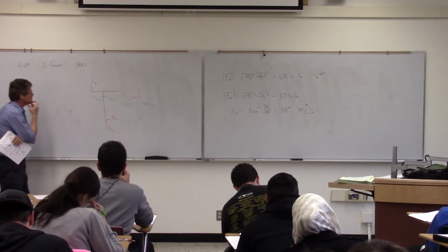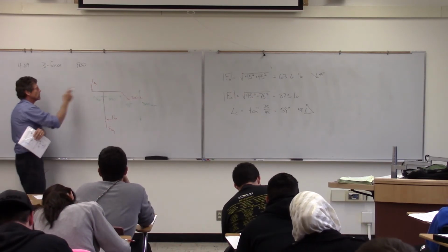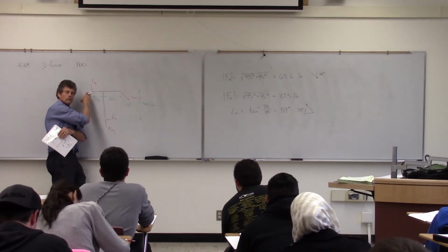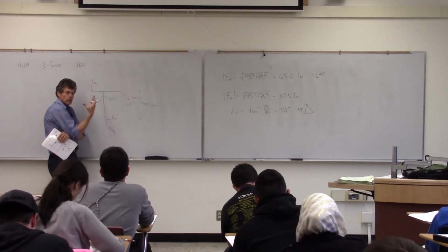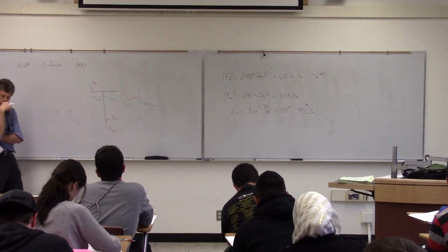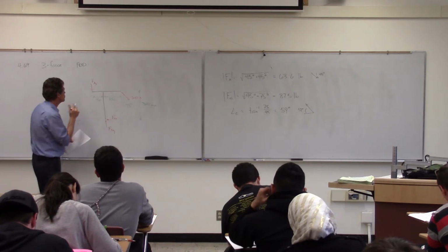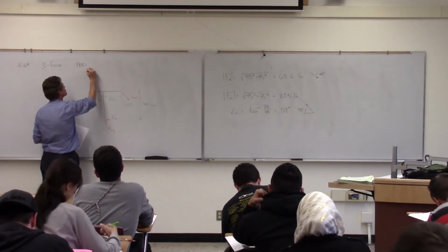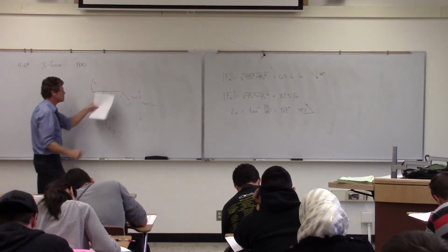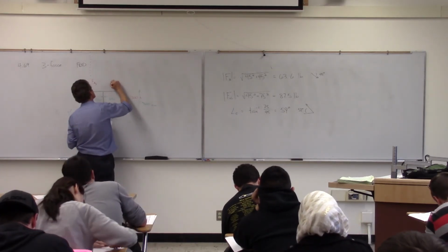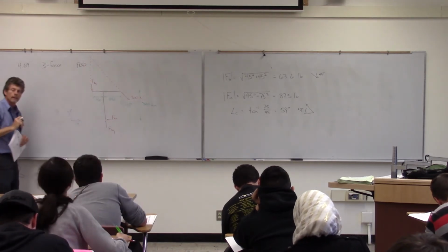Okay, so I've kind of given it away here in terms of talking about it being 3 forces. We've got a force here. We've got a force here. And then we actually have a single force here. I've just shown it in component form. So 2 of the forces I already know directions to. This one's perpendicular, so its line of action is doing this. And my second force is at 45 degrees, so it's doing something like so.